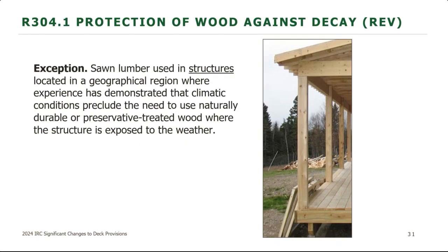There is an exception for geographical regions where you don't have decay, but that section was just changed so that instead of saying buildings located in geographical regions, it now says structures located in geographical regions, because you could have a deck just built out in the middle of nowhere in a geographical region where you don't have decay issues, and that would not qualify if it just said buildings. So now it was changed to structures.